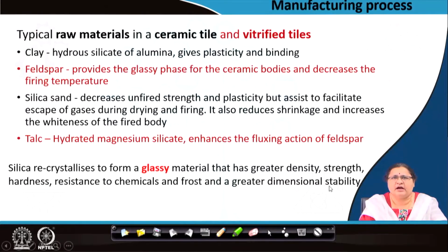So let us now come to the manufacturing process. How are they manufactured? How are they different from the making of a brick? Here you can understand that the raw materials have to be very fine and they have to be consolidated or compacted to a great extent, so that the porousness which was prevalent in bricks, allowing some 15 to 20% absorption of water, is prevented.